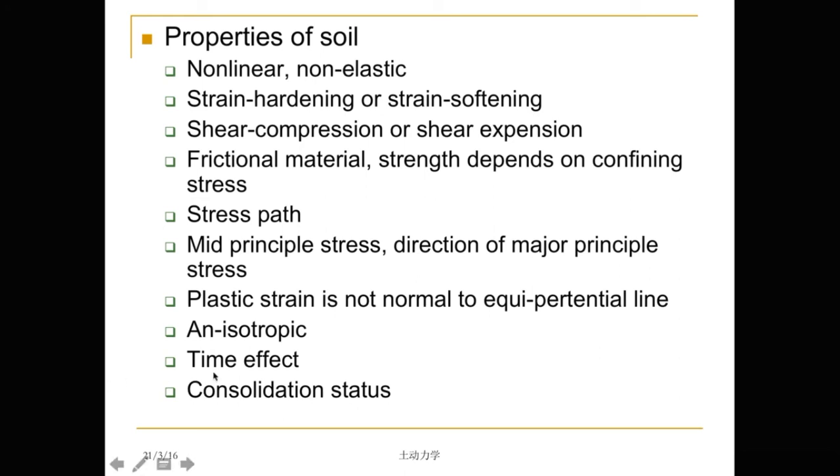And another is time effects. We know in the soil there's pore water, and in the water there are some chemical materials, and after a long time, these materials will create cement between the soil particles.